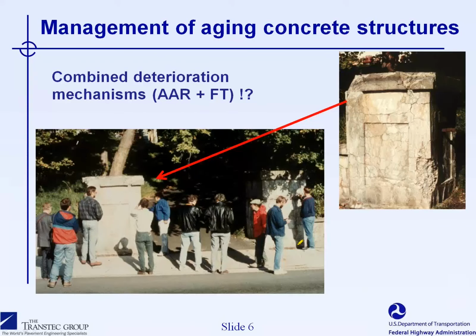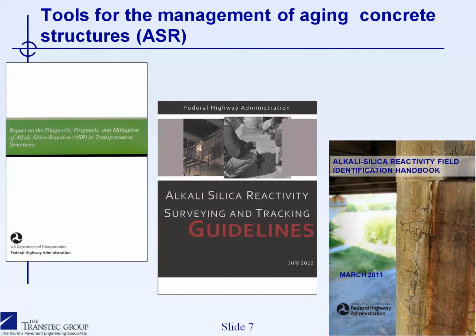It is also quite critical, especially in northern states or countries where ASR develops, to consider that it is not only one action or mechanism involved. Like in this case here, you can see cases of ASR and freezing and thawing that are affecting some concrete elements, and with time ASR is obviously increasing the internal deterioration in the concrete element, but freezing and thawing action is certainly a major factor contributing to the distress, at least at the surface layer of the affected concrete element.